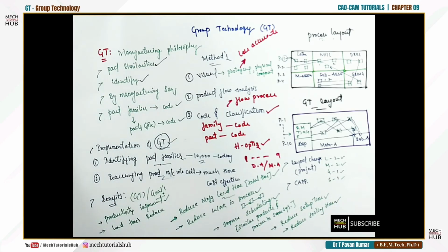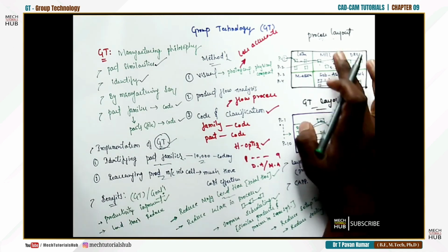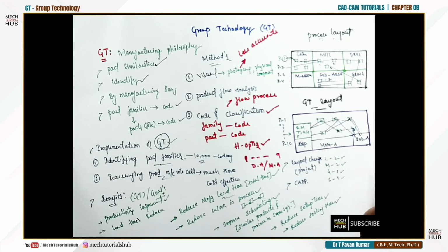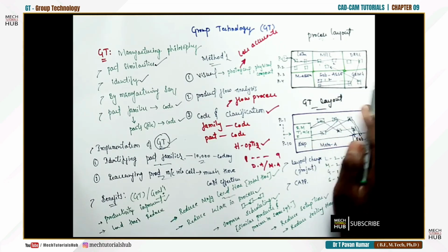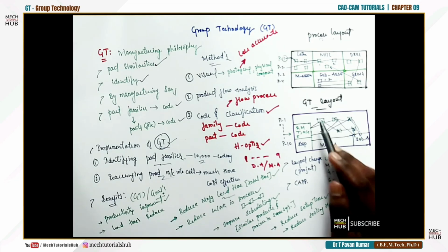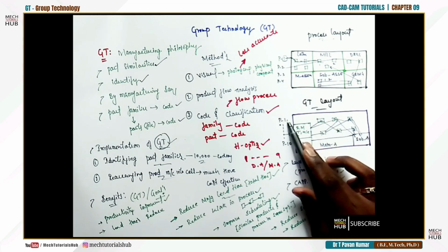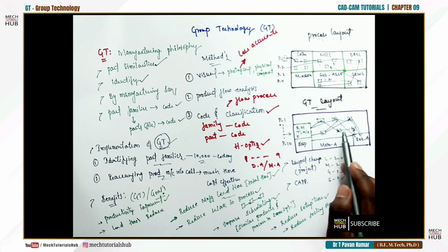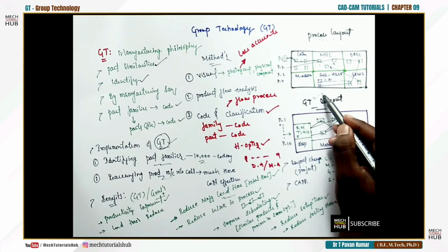Finally, I would like to conclude that group technology is a manufacturing philosophy that helps you know the similarities among the components and group them in a family, which will help you in further sequences. Group technology can be implemented if there is computer-aided process planning in the firm. There are many other benefits. I tried to explain the process layout and group technology in a different pattern, with the traditional way and group technology implementation. In the traditional way, the shop floor layout will never change, whereas after group technology implementation, the shop floor layout will change, and the time each part consumes on each machine, the time when it reaches the next machine, how many machines are required, and what tools are required, everything is set. That is what I tried to brief.